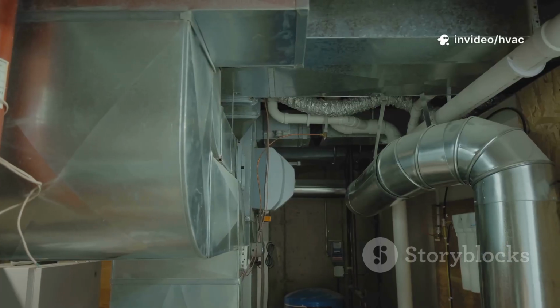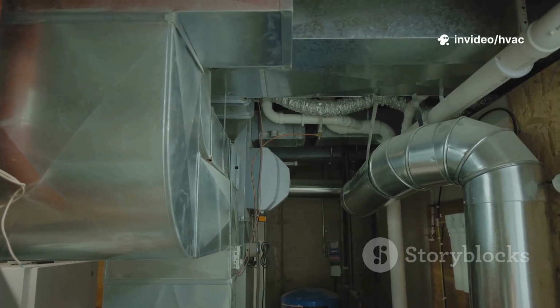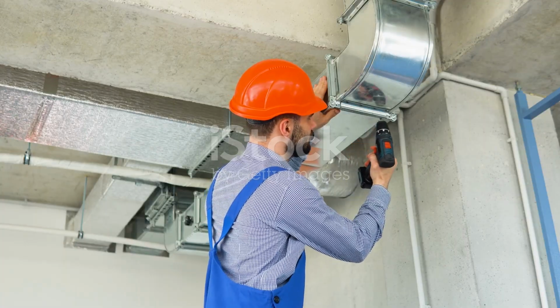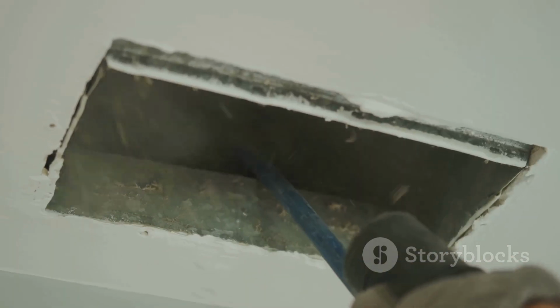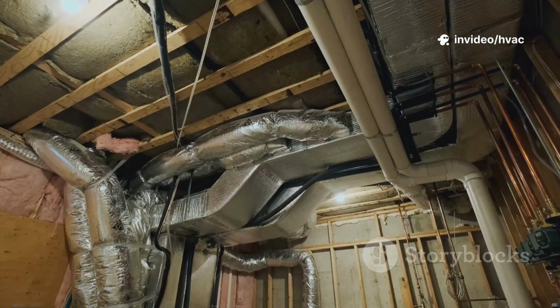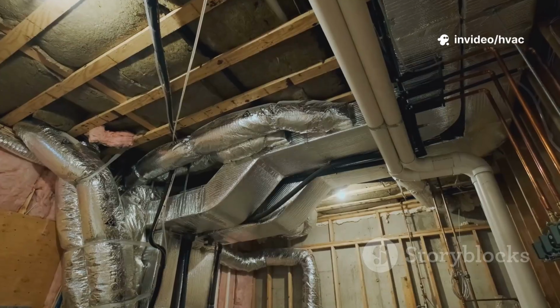For big ducts, install the sensor in a zigzag pattern to cover the area. Rule of thumb: 1 foot of sensor for every square foot of duct area. Too short, and you miss spots, leading to bad readings and higher costs. Do your homework, measure, calculate, and choose the right length. For example, a 4x5-foot duct needs a 20-foot sensor.